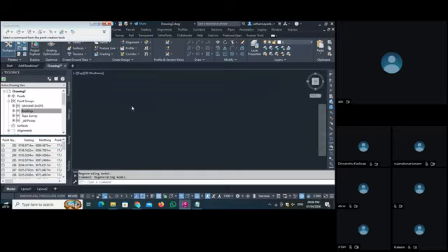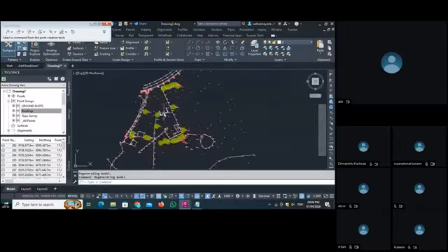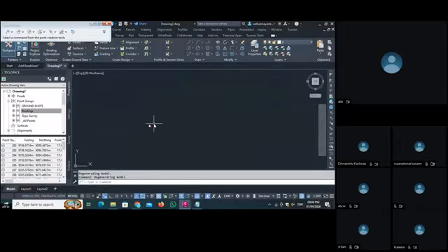As they see the duplicate number, it will show on this point somewhere else, but our original point is shown here. So whenever you import two files, you have to make sure that you import all files in the same manner, or you may have some mistakes in the points.